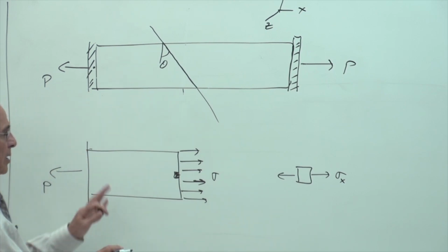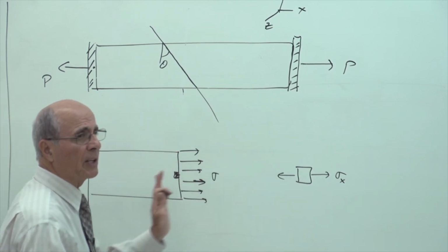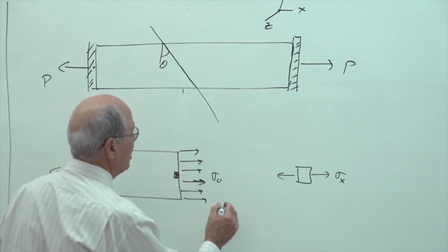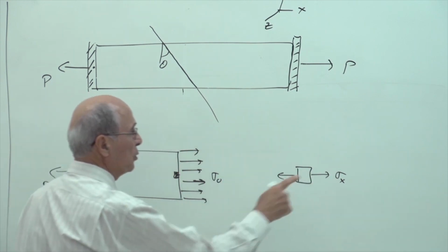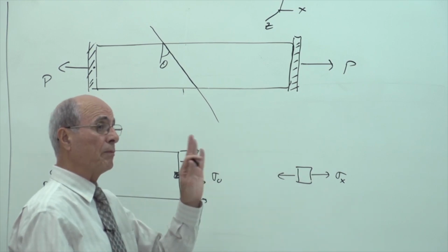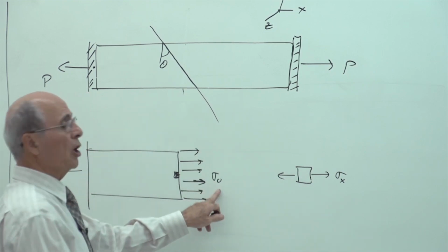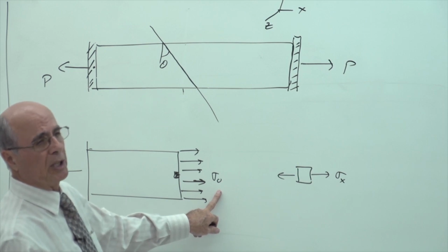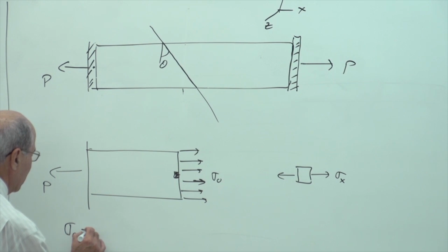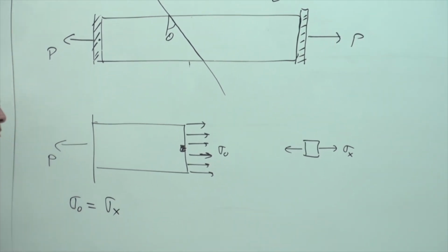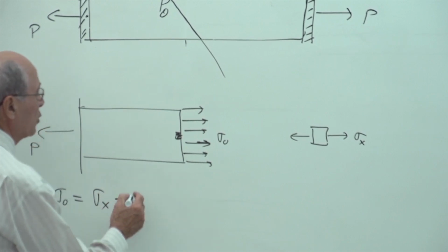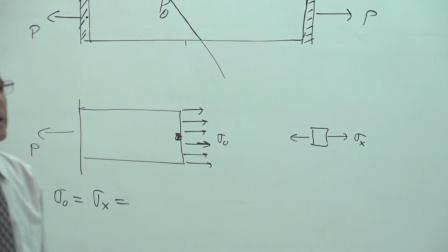So this is the state of stress at that point. As I said, don't worry about it. All I'm saying is that it's a pull that way, all the way across here. This sigma, let's call it sigma O, or in future, in chapter 7, we are going to call that sigma X. This is in reference to the future lecture. In the book, they are showing you sigma O or sigma original. Is that correct or not? So let's say that sigma O, or sigma original, but for future reference I'm adding that to the system. You want to write this down, is equal to force over area.